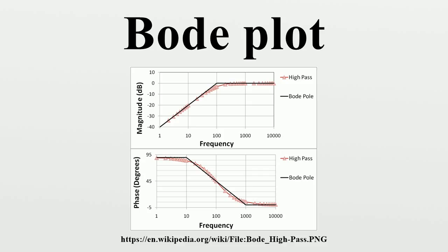Given that the decibel is itself a logarithmic scale, the Bode amplitude plot is a log-log plot, whereas the Bode phase plot is a lin-log plot. As originally conceived by Bode in the 1930s, the plot is only an asymptotic approximation of the frequency response, using straight-line segments. However, with the advent of computing, it is often taken nowadays to mean the precise plot of the actual frequency response.